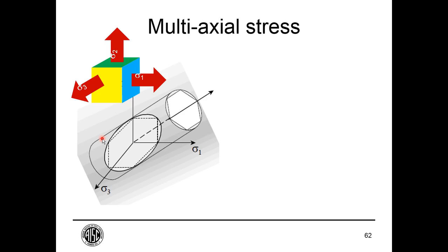Now, often we have strain not just in the longitudinal direction of an element, but we might have strains that build up transverse to that principal strain. So if you recall von Mises' interaction formula, there's an interaction between principal stresses in the orthogonal directions on shear as well, and you form this yield cylinder.